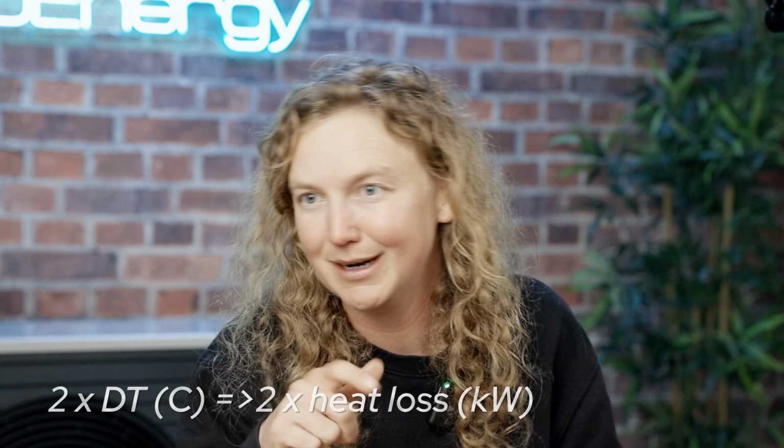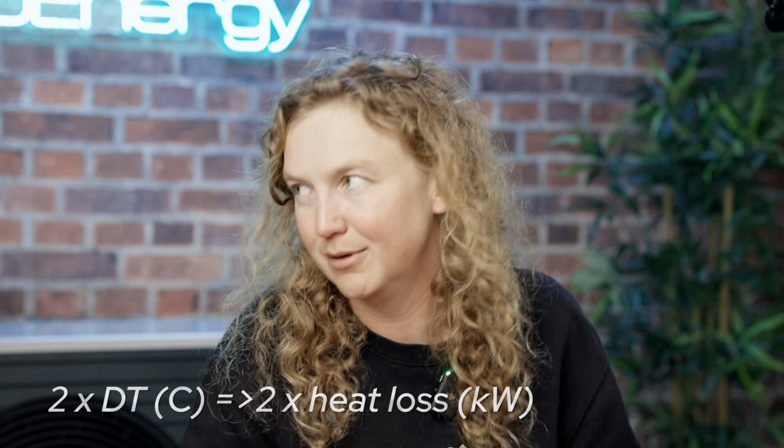Is the heat loss a fixed number? Because we talk about a property having 8 or 10 kilowatt heat loss. We have a changing temperature outside, right? How does that work? Yeah, exactly. So although we talk of heat loss as if it's one number for one building, actually how quickly the building is losing heat is always changing depending on the temperature inside and the temperature outside. So, if it's 10 degrees outside, 20 degrees inside, versus it being 20 degrees inside, 0 degrees outside, we're going to have double the delta T, double the rate of heat loss.